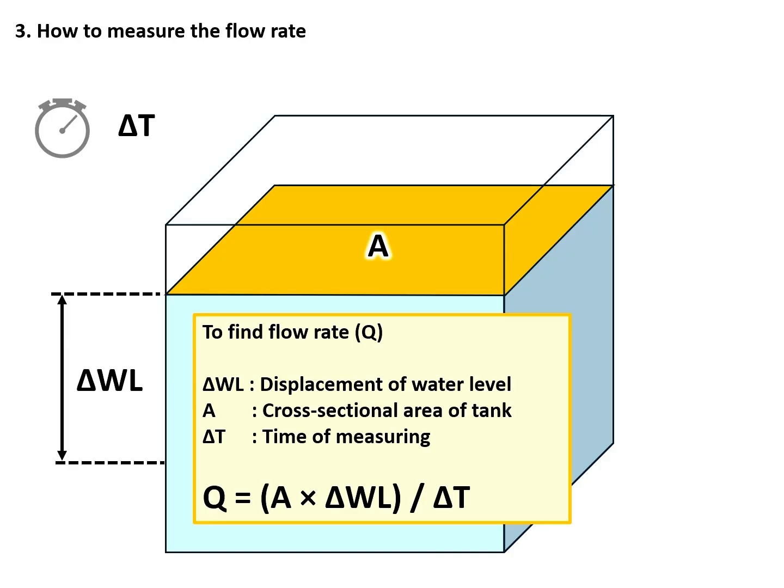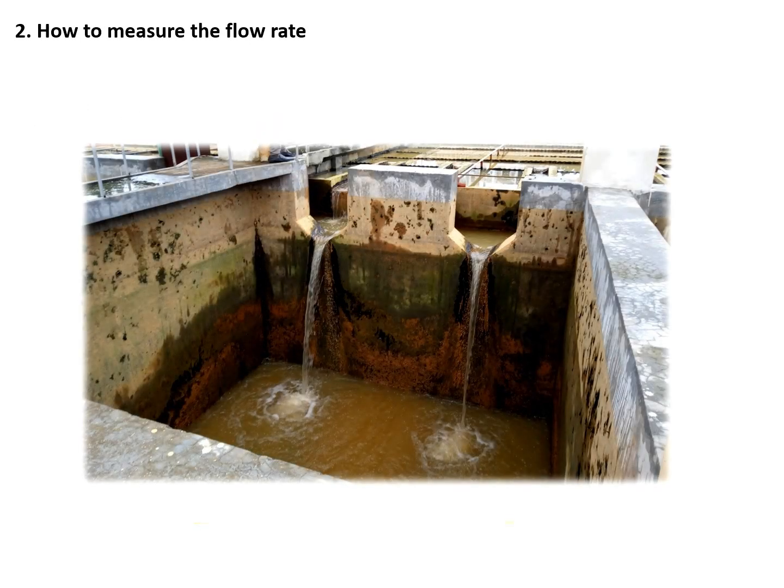It is possible to incorporate this methodology at water treatment plant. Shut off the valve right after filtration so that water can be reserved in the basin. By observing the water level and time, the flow rate can be calculated. In most cases, several pumps are running simultaneously and there are multiple filtration basins at the plant. To make it accurate, those conditions should be considered.